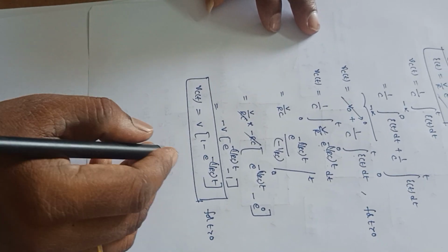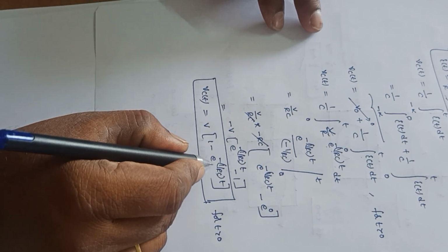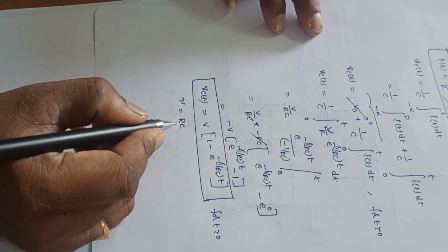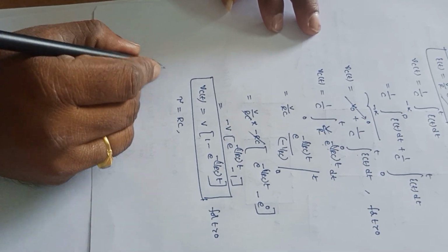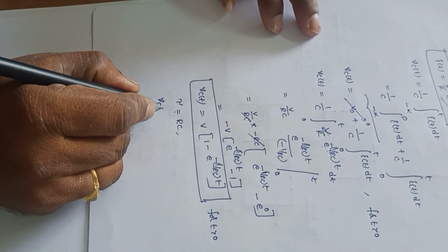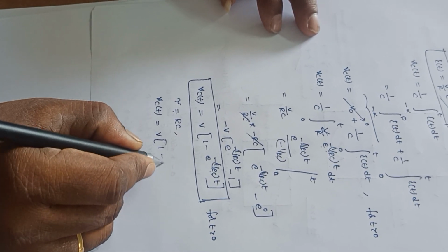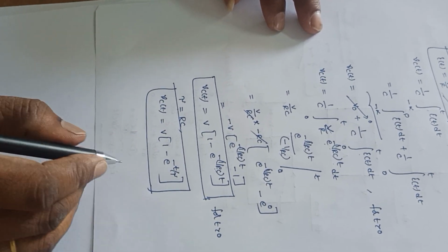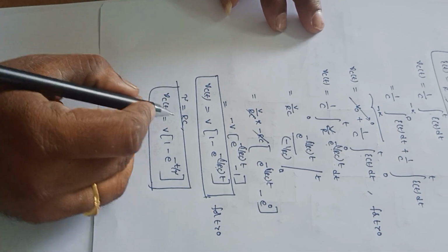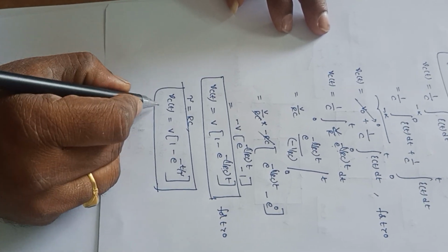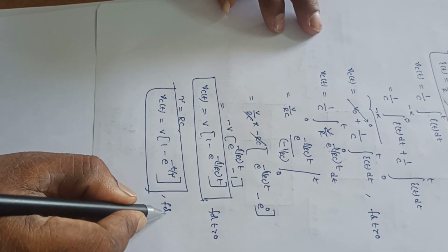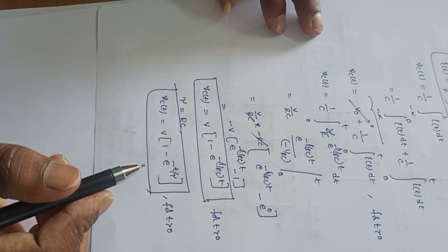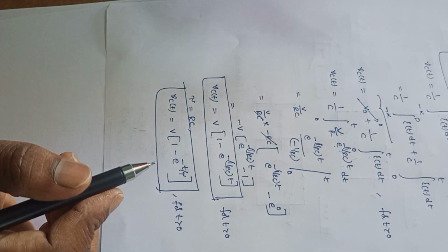And here I need to define the time constant. So the time constant tau is equal to RC for the RC circuit. So you replace this RC with this tau, Vc of t is equal to V into 1 minus e power minus t divided by tau. So this is also an expression for the voltage across the capacitance, and it is okay for t greater than 0. We already defined the time constant in the last video while I explained about the RL circuit transient analysis.